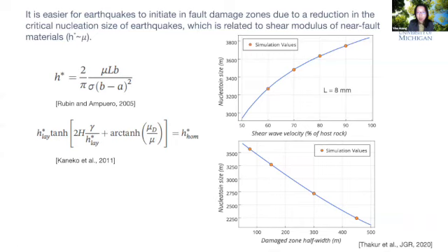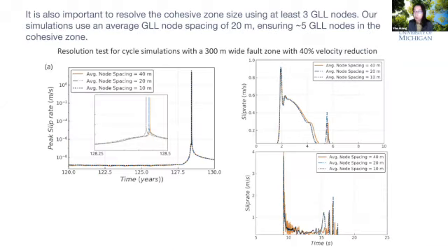And for the simulations I'm showing today, we are going to focus on those narrow fault zones first. So for those narrow fault zones, the theoretical nucleation size is about 3 kilometer, which means that the W over H star ratio is about 3.5 for these simulations. And for this W over H star ratio, we are going to observe mostly periodic occurrence of large earthquakes.